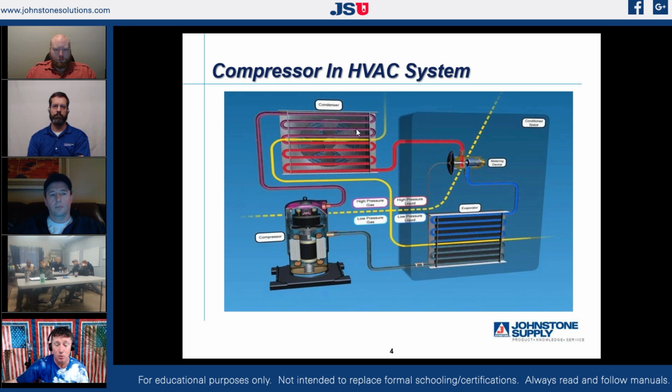On my evaporator coil, instead of moving air as in the air conditioning system, what if I'm pumping water from a trough and recirculating that over that evaporator coil? I'm still transferring heat. I'm actually removing heat out of my water to assist that boiling process until my water gets down below freezing, and then I have a slab of ice on my evaporator.